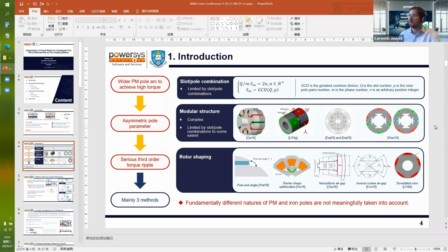Next question is the issue of torque ripple associated to machine control and drives, like time harmonics of the armature currents? Yes, for the control side, since in the simulation we use the standard sinusoidal current waveform, we just ignore the current harmonics.